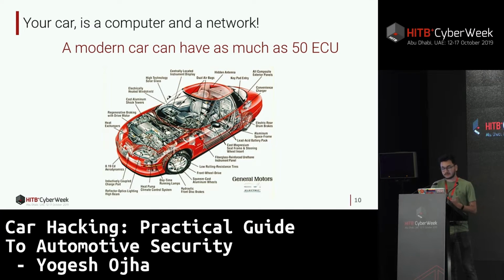In layman's terms, what really happens in a CAN bus is that the messages are sent on a bus, and the CAN network never determines who is the receiver. All of the receivers receive the message and find out whether it is intended for them or not. They have something called an arbitration ID, the receiver's ID, and then they find out whether that particular message is for them or not. That's how it generally works.